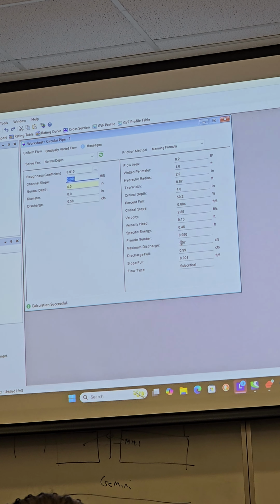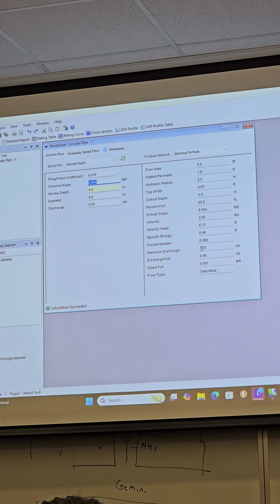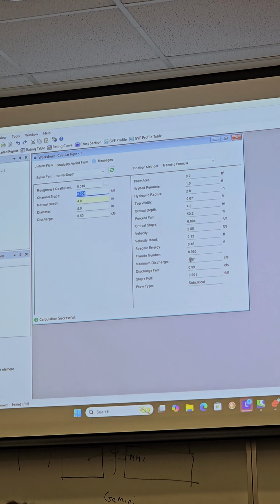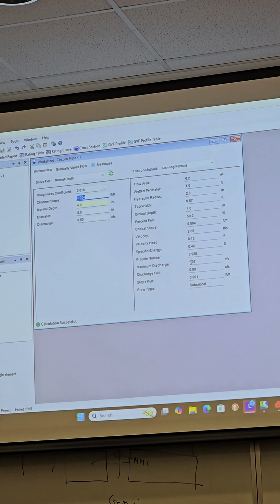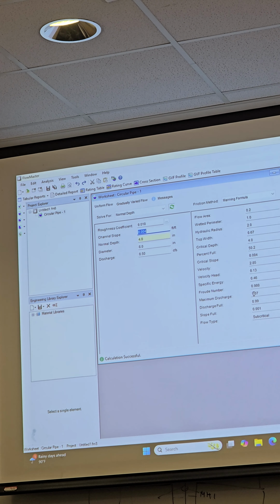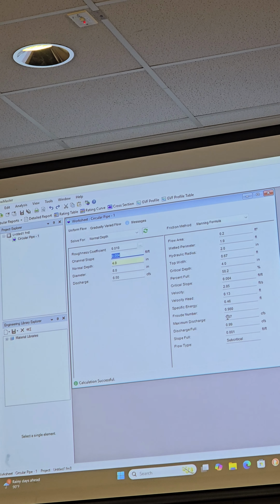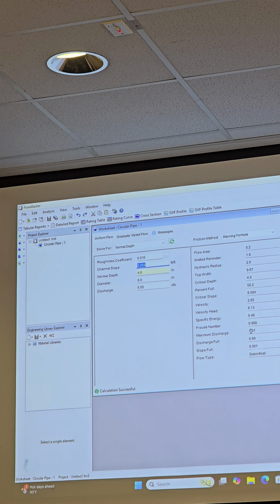Yep. And just to be sure, we're trying to keep the slopes the same along every pipe segment. You don't have to do that. I mean, the thing you've got to think about is, your existing ground is at a certain slope, right? So you have to just think about the slope of your pipe relative to that ground, because you've got to maintain a certain depth of your pipe.